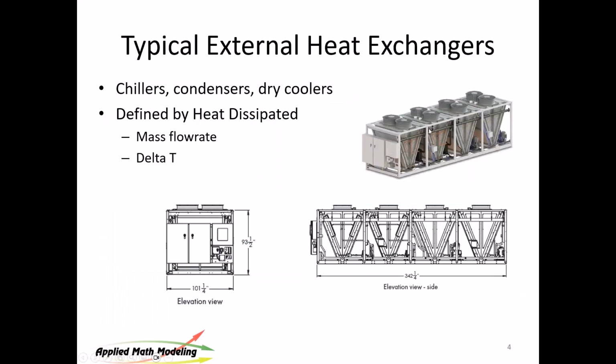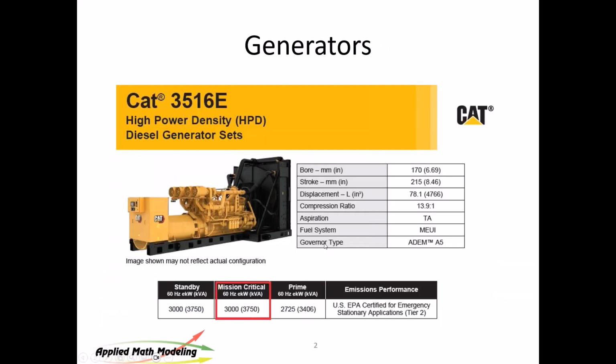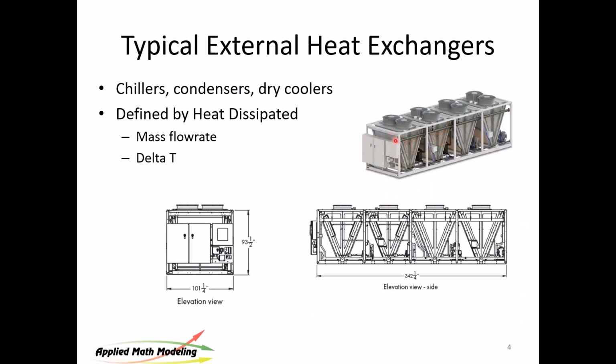Now, it's not perfect because you see these are angular and this is flat. But in the greater scheme of things, what you're looking for is what's the approximate temperature coming into these devices. And here we're going to get the approximate temperature of that inlet of that PDU, or in this case, HDU. Now here, you would really want the temperature along these sides, but again, these are not constants, they vary, and the reason we're doing it rectilinear instead of as an angle is mesh size, mesh count.